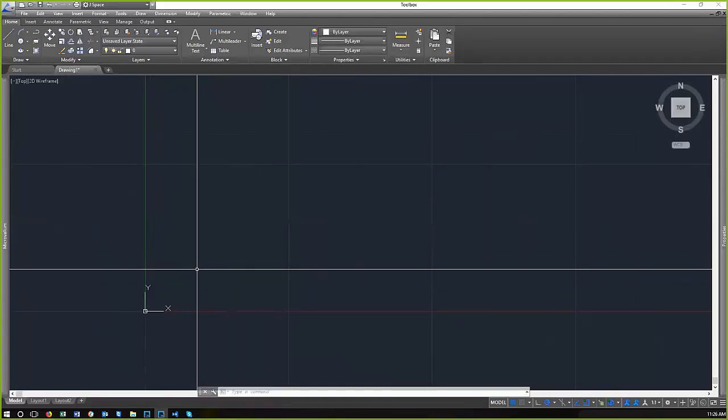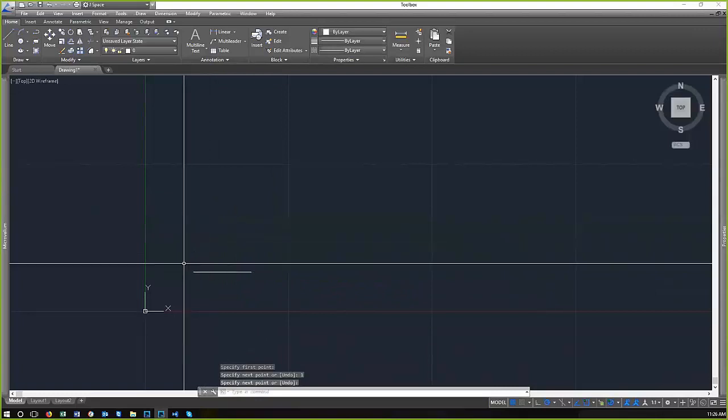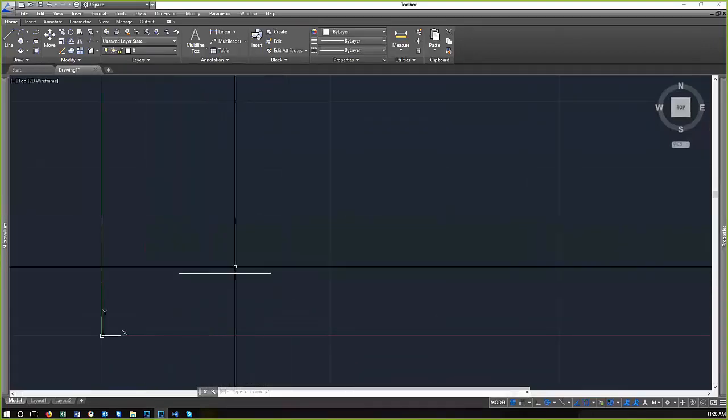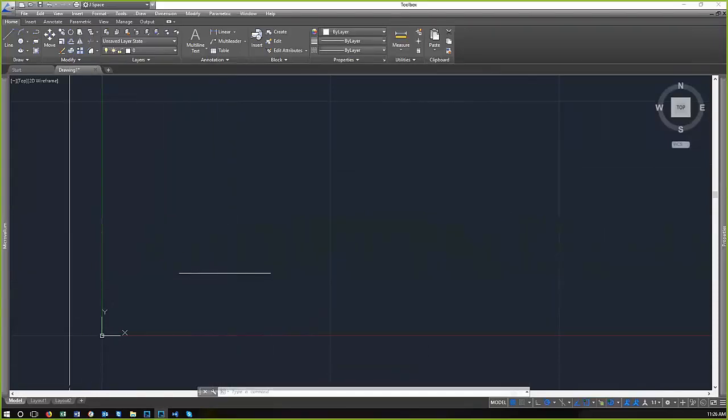So it's 1 unit, whether you've selected metric or imperial units, it's just one of whatever unit that you have selected. So if you draw a line that's 1 long, depending on what you're using, it's going to be 1 inch, 1 millimeter, or perhaps 1 centimeter long. So model space doesn't care what size or what unit you're actually using. Paperspace takes care of that.